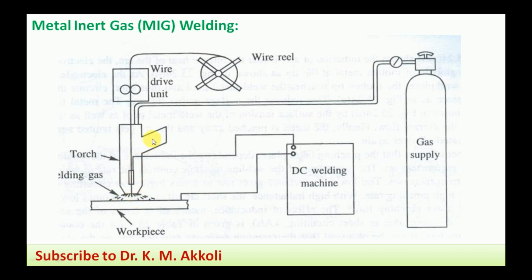And later, whatever the gas is there impinges over that molten metal pool, and that provides a sealing gas that protects it from atmospheric contamination. Initially, continuous welding will be carried out, and later the arc will be separated for a few seconds and extinguished, while the supply of the gas continues. That provides the sealing of the gas. Thereby it also provides clean welding, and it is mostly automated, not manual.